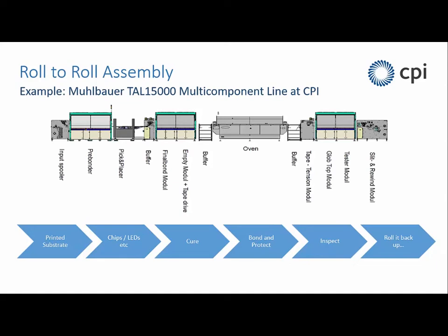And the thermodes are doing the anisotropic conducting adhesive bonding process. And so something like 64 individual heat elements are pressed down onto components, arranged in the appropriate arrangement, so that you can bond a whole set of components simultaneously as this device goes through. And it's all a stop-start sort of approach.